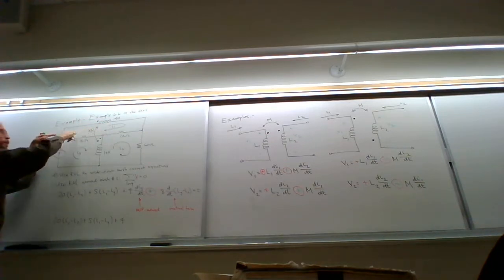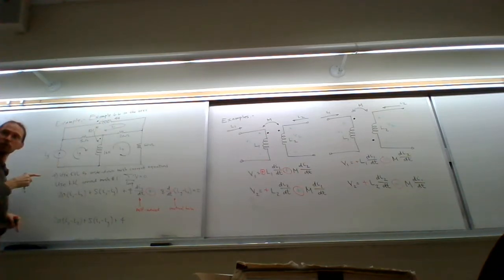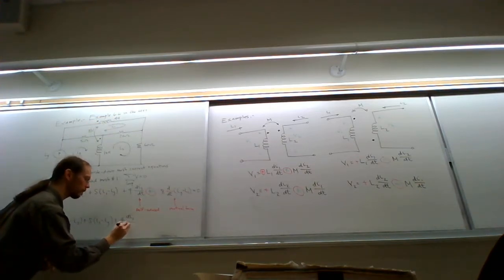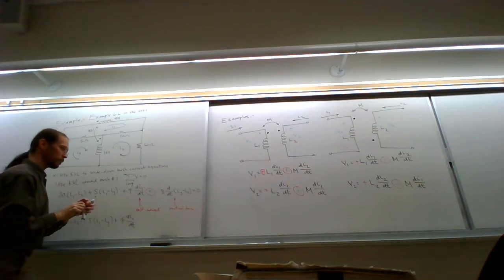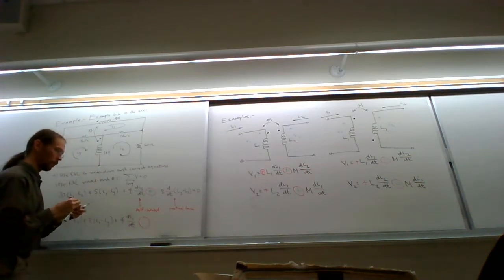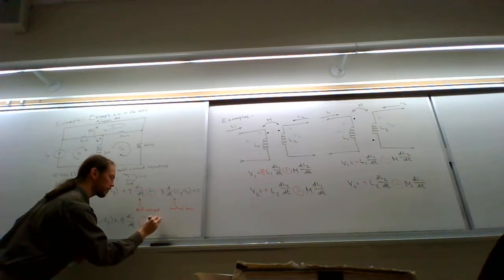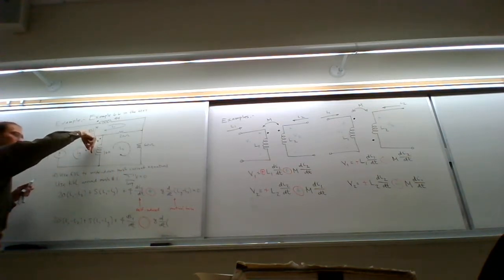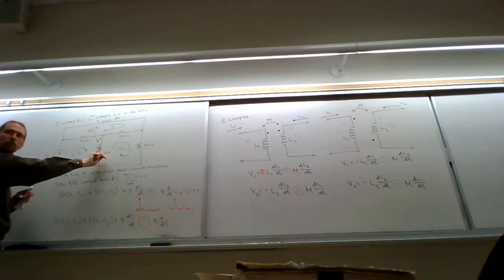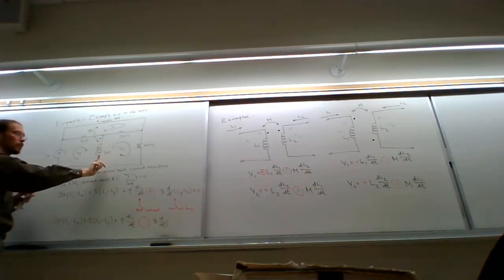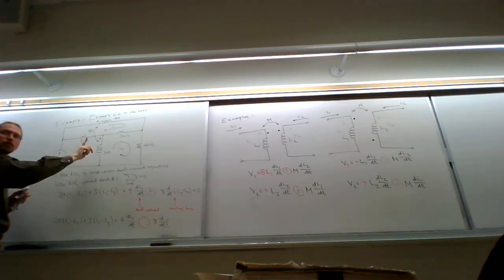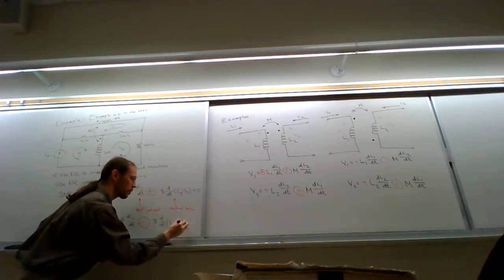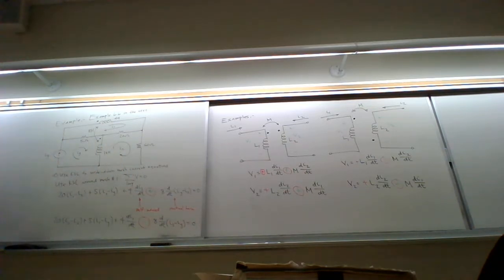Now I still, when I go through this, I still have a self-induced voltage, and it's 4 henries times di1/dt. But now for the mutually induced term, I'm going to have the mutual inductance times the time derivative. Now I'm going to say that the net current is not going down this way, it's going up that way through this inductor. That means that the net current is a superposition of I2 and Ig, and it is I2 minus Ig. That has to equal 0.